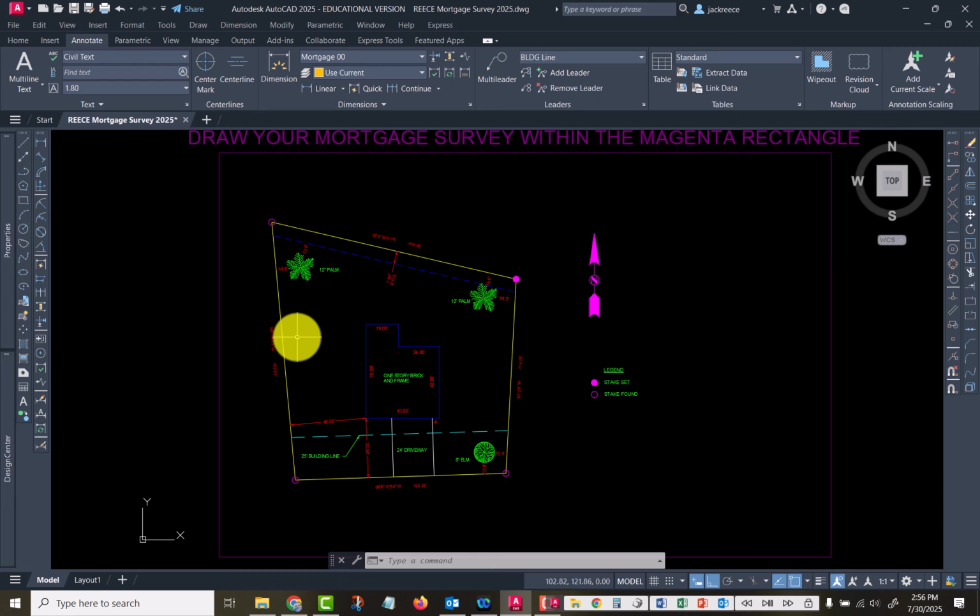Let's see, the line type scale, I'm pretty sure I set that. Yeah, I set line type scale at 18 already, like the book showed you. So follow through the first few pages of the exercise and just check and make sure that I've got things set correctly. And then you start drawing. Now when you draw the lines, in step 8, it says turn off your dynamic input. That way you can just type in the distance and the bearing.